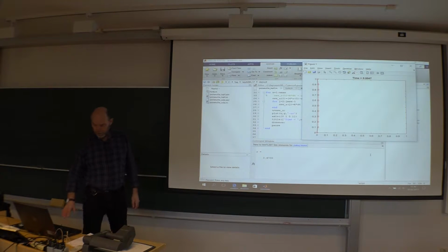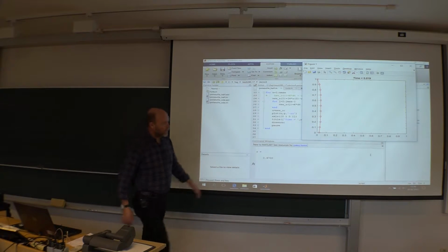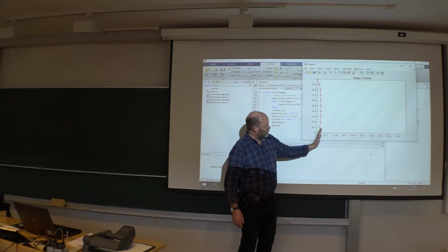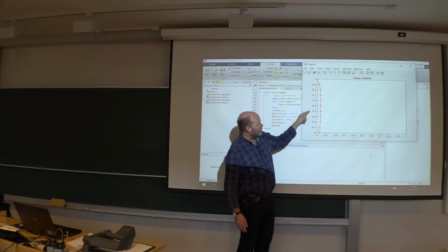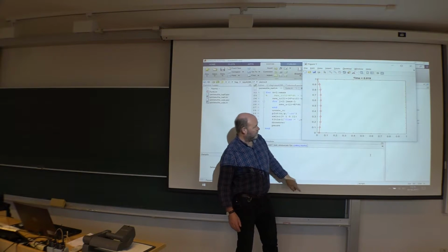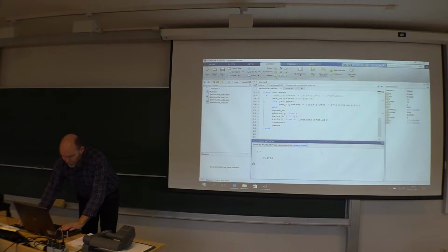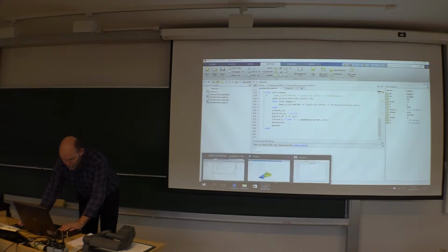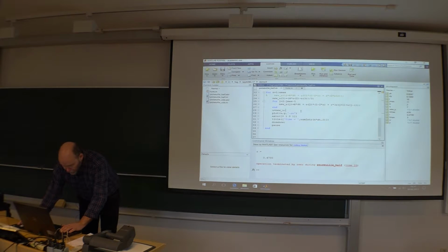First time step, second, third. Then you see down here at the symmetry line, it should be straight. Something is wrong here. It has gotten an angle. So this is going to be a very strange velocity profile, sort of a double, little erratic. So clearly something is wrong with my boundary conditions here. So how can we fix this one?